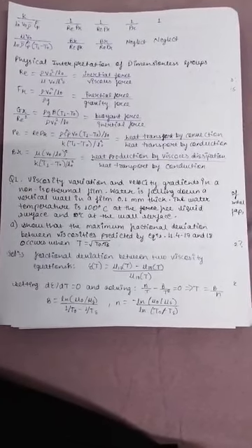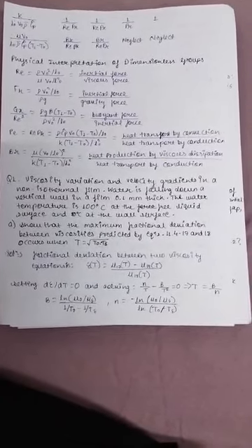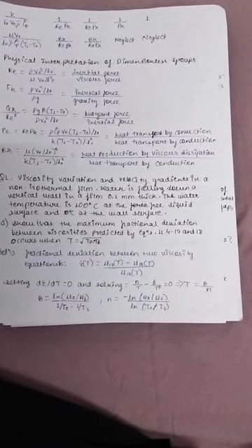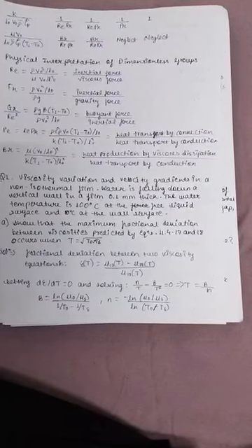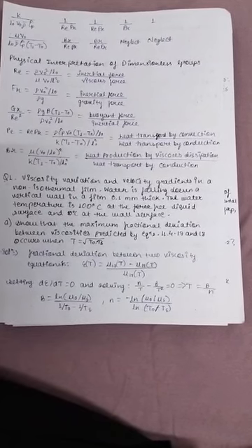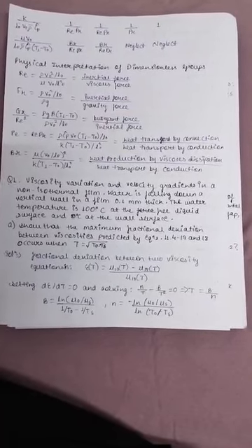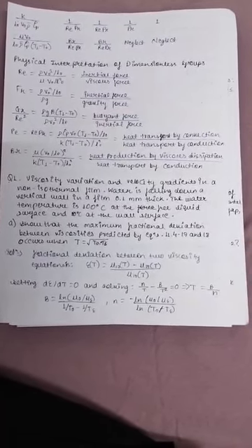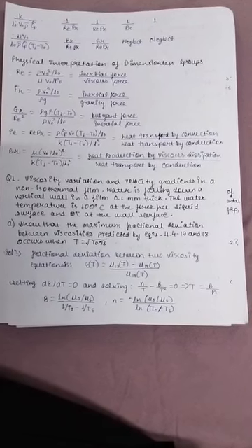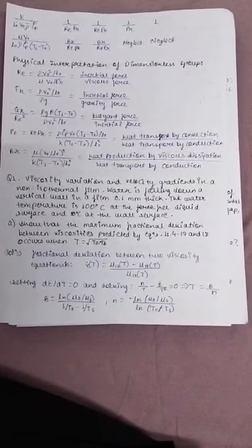Now the physical interpretation of these dimensionless groups. Reynolds number Re equals rho V naught squared over L naught divided by mu V naught over L naught squared, which equals inertial force over viscous force. Froude number Fr equals rho V naught squared over L naught divided by rho G, which equals inertial force over gravity force. Gr over Re squared equals rho G beta (T1 minus T naught) divided by rho V naught squared over L naught, which equals buoyant force over inertial force.